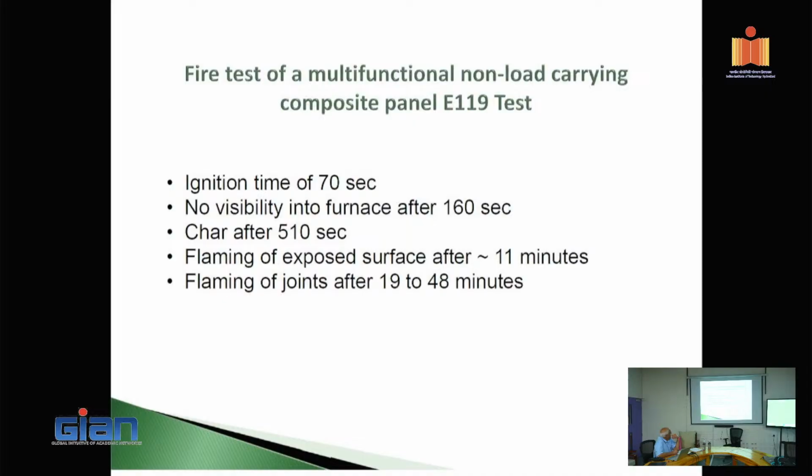So we developed a multifunctional load-bearing panel. The ignition time is 70 seconds. No visibility, the opacity I was talking about, is at 160 seconds. That's almost 3 minutes. After that, you cannot see. So up to 160 seconds, you can see and get out.